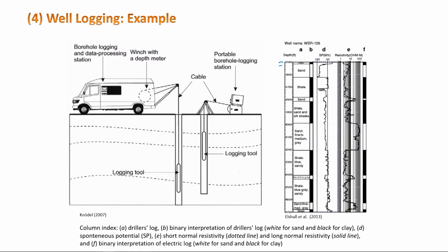What I wanted to tell you here is that you can also do electrical resistivity or other types of borehole survey, borehole logging. So the driller, as a bonus, did borehole geophysics for us, and that's a bonus because it's very cheap. This borehole geophysics costs about 100 euros, while drilling costs 20,000 euros, and it's done very quickly. You do it in 10 minutes, or 15 minutes, because basically